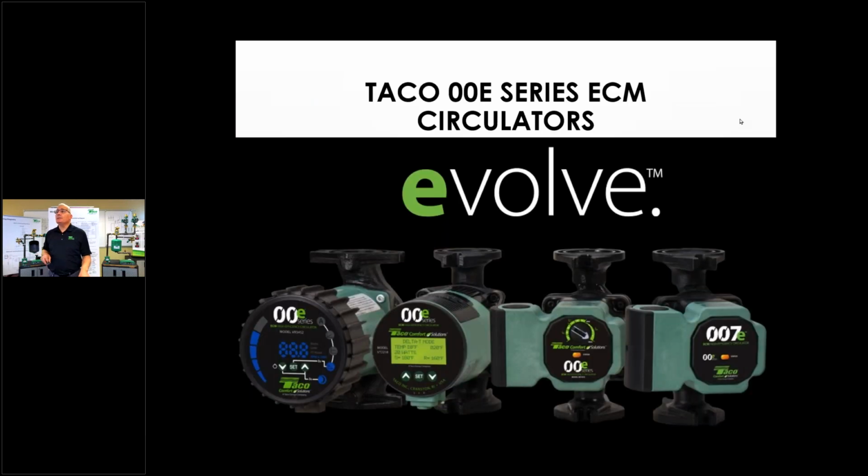Take advantage of it. ECM series circulators. We've been talking about this now for quite a while. The line keeps expanding. TACO just introduced the 0026E and 0034E. So now we have ECM circulators that can replace all of our 00s. The 26E and 34E can replace the 10s, the 11s, the 12s, the 13s, the 14s, and even get us into light commercial, okay? Take advantage of circulators like this.